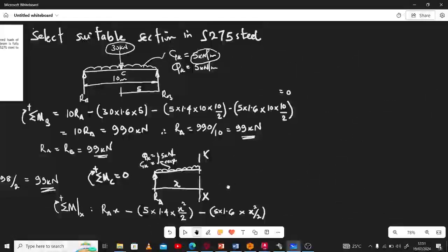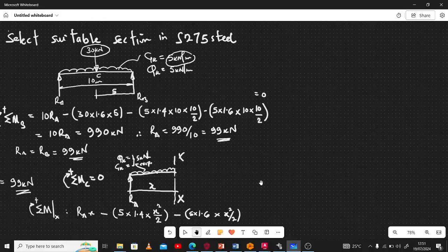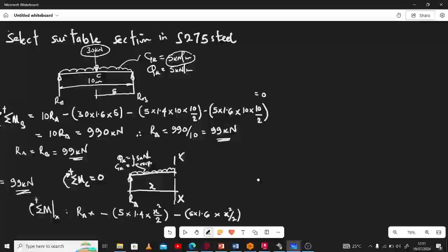we just want to carefully continue on the side. We have RA known already, and every other one we do not know. So when our x is equal to 0, for example, the moment at A will be equal to 0 kilonewton meter. When our x is 5, which takes us to the mid span where we'll have the maximum moment, we'll have 5 RA